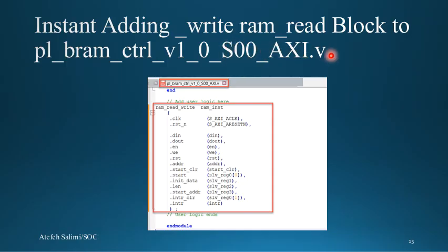And as you could see, the type of the file that has been generated by the tool is Verilog, but it is totally dependent on the default setting that you apply whenever you start creating the project. For example, in this project, we didn't change the default setting, and by default it will generate Verilog. But if you are familiar with the VHDL coding, it is better to change it at the start of generating the project.